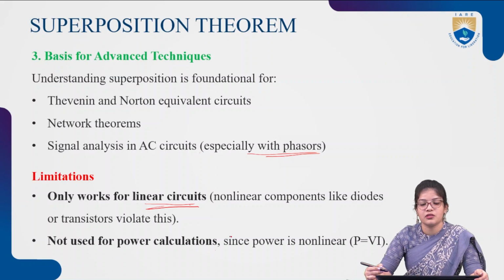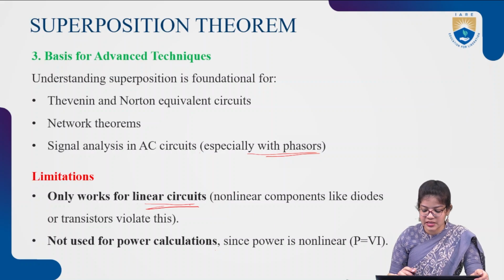The superposition theorem is used only to calculate currents and voltages. It is not used for power calculation since power is non-linear, so we cannot calculate power by using superposition theorem.